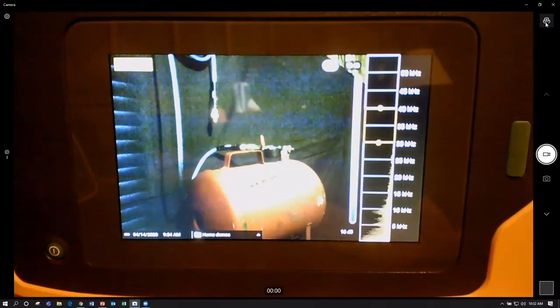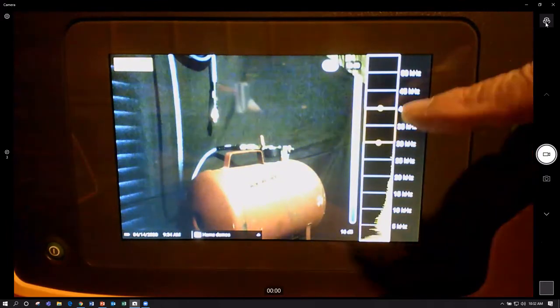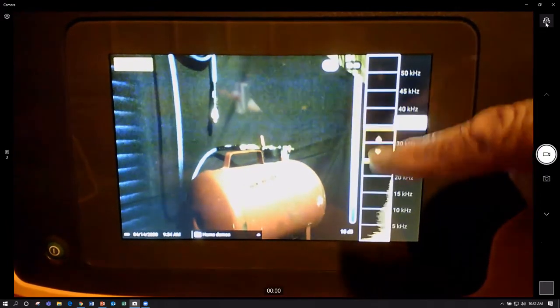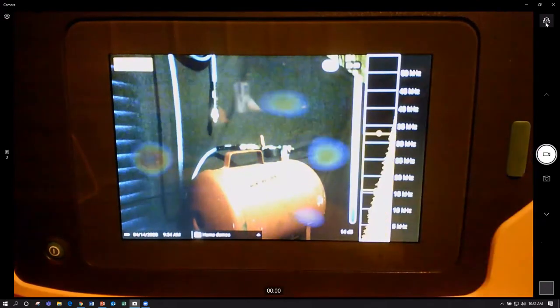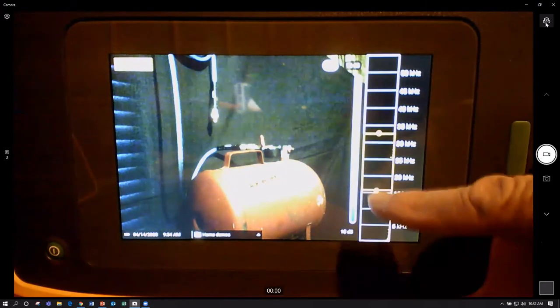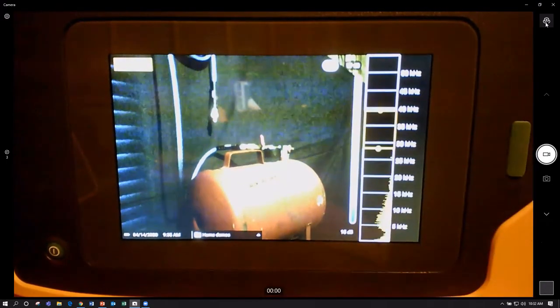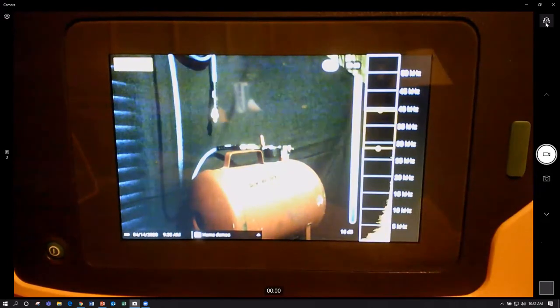But we're only creating the sound map. I've got it set now, it looks like 30 kilohertz to 40. If I slide this down, now when I make noise, you'll see it light up on the screen, right? Let me squeeze that down again, kind of raise it up. And I'm going to turn the air leak back on.